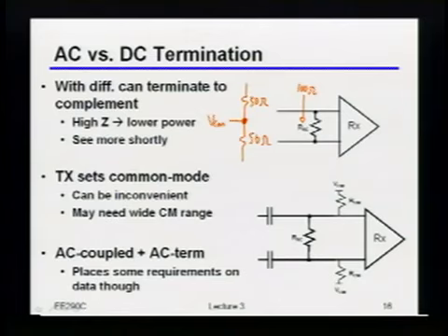But there's one more trick you can play, which, as I said, at least over a certain range of frequencies, gives you the termination. The inductor? Okay, I heard a few different options. I think I heard inductor. I think I heard the right answer. Capacitor? Yeah, capacitor, right? If I put a cap here to ground, then at the frequencies where the cap kicks in, it actually looks like a good common mode termination, right? And indeed, that is a pretty common technique that people will use.